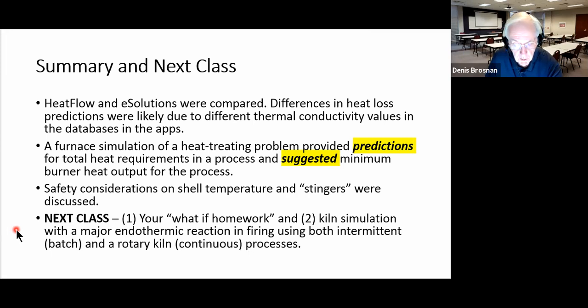By manipulating e-solutions, I think you'll have a little experience in practice in furnace lining design and what creates more efficient production, either by using more of the volume that you have in the furnace or by using a different insulation scheme to reduce heat storage and heat loss.